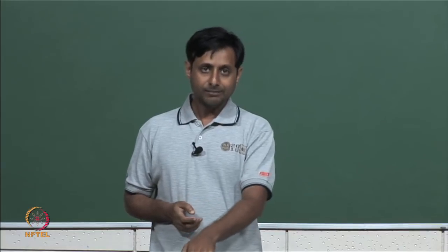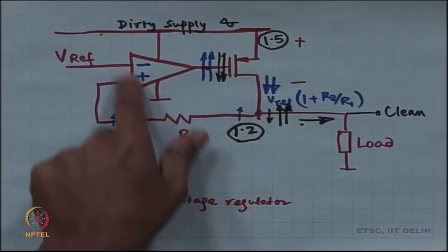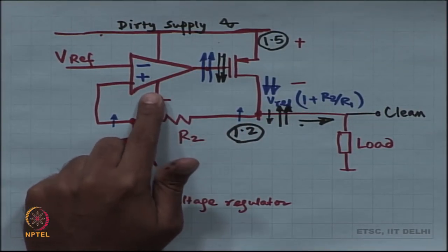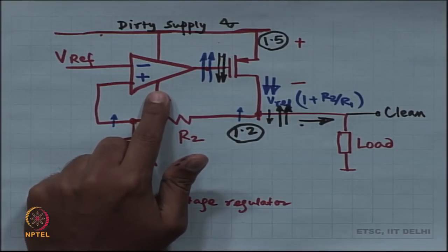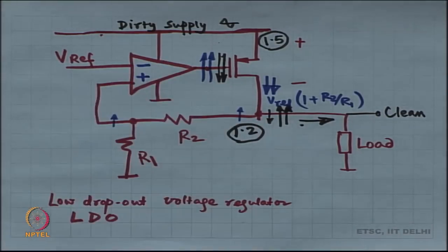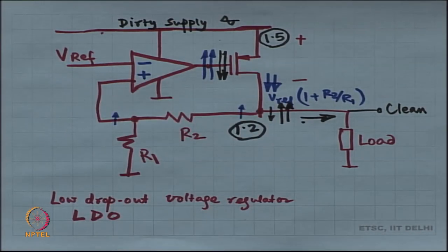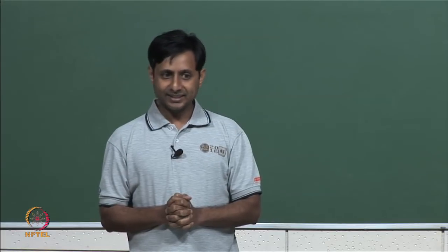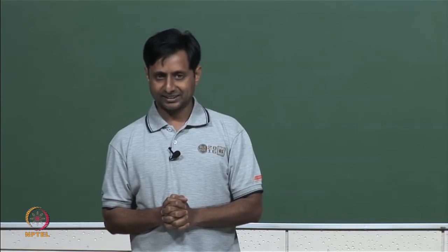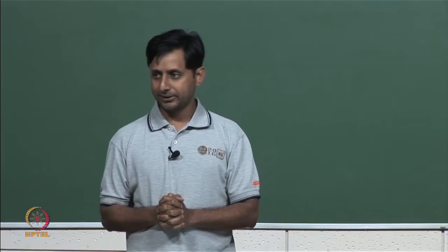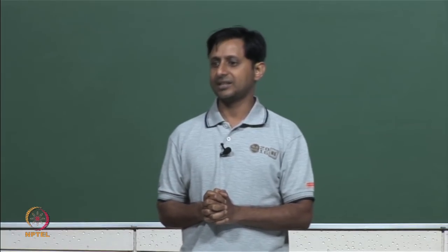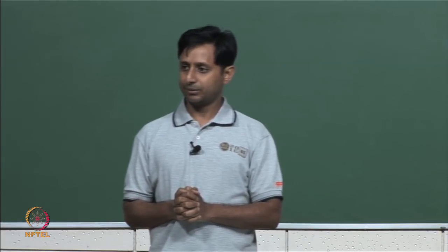A lot of people avoid that just by making this a 1 stage amplifier, right. They say let us not bother with a 2 stage amplifier, let us make a 1 stage amplifier over there and sort it out, and then they compensate this overall. Okay. So, we will discuss these things and more in the next class, when we further talk about voltage regulators and start looking at the frequency response.